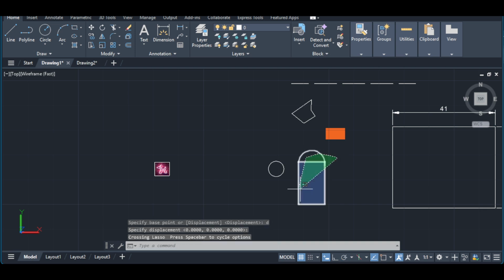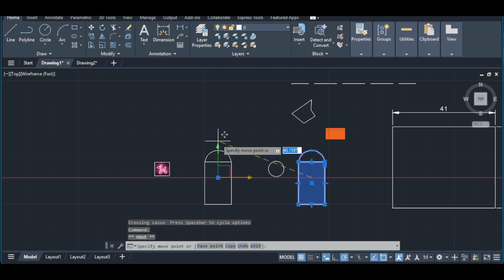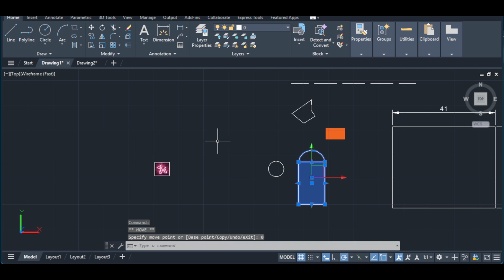If you're working in a user coordinate system, 0,0,0 refers to that system's origin. If you need the world origin instead, make sure your current coordinate system is set to world before you start. You can confirm the move by looking at the UCS icon or by zooming in near the lower left corner where the axes intersect. A couple of quick tips.